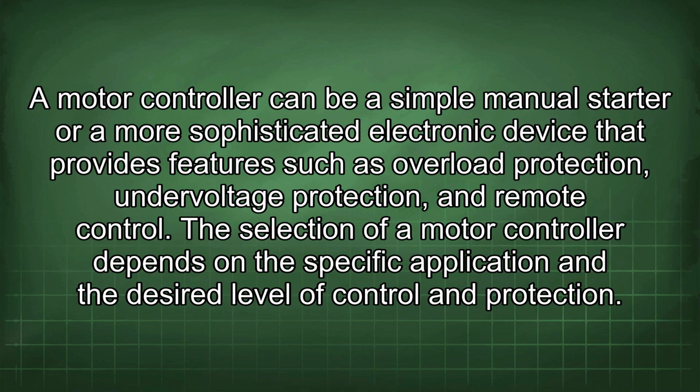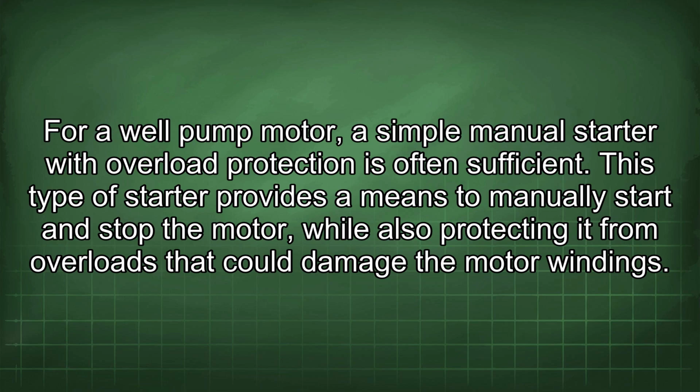The selection of a motor controller depends on the specific application and the desired level of control and protection. For a well pump motor, a simple manual starter with overload protection is often sufficient. This type of starter provides a means to manually start and stop the motor, while also protecting it from overloads that could damage the motor windings.